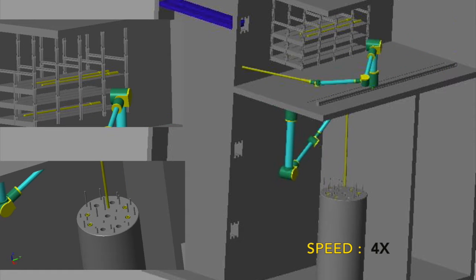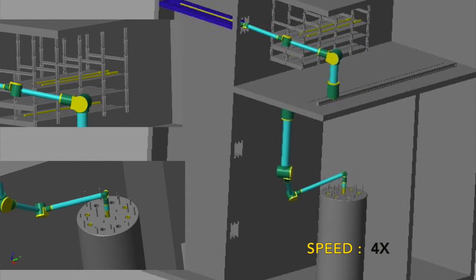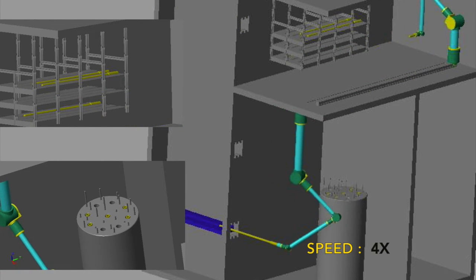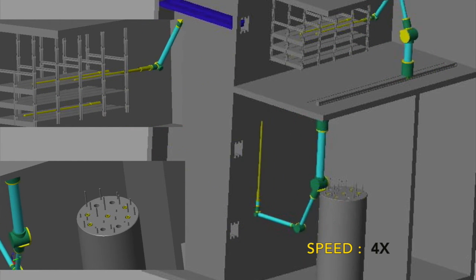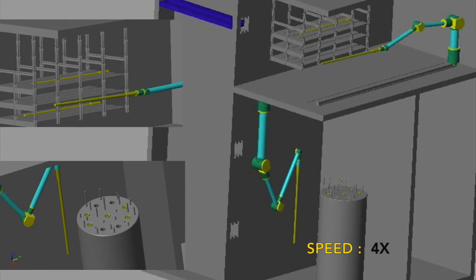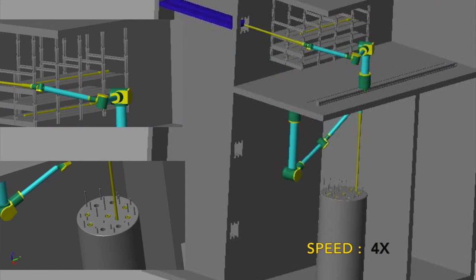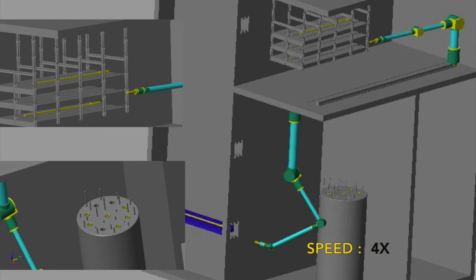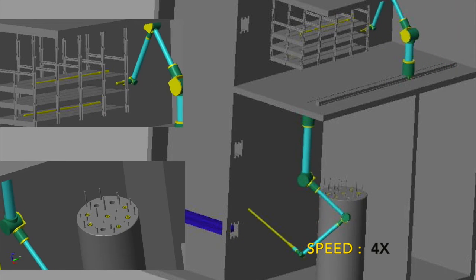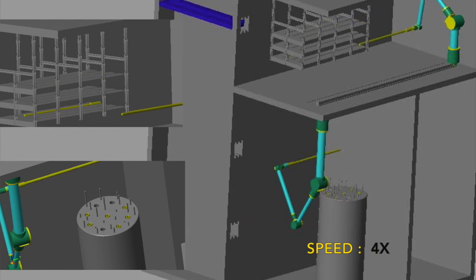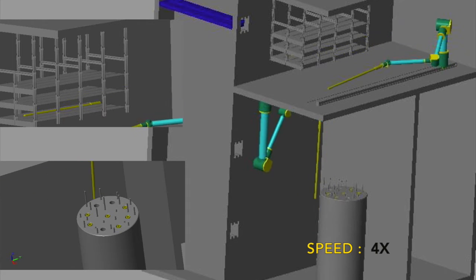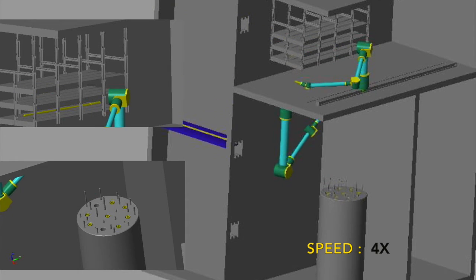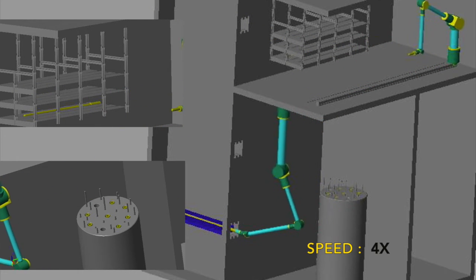The simulation was created in SimMechanics. All the given models for the room and the joints were exported from SolidWorks to SimMechanics in the form of a STEP file. The 2 robot models are built with the desired parameters using SimMechanics transform and joint blocks. A time series data is generated from the MATLAB script, and it is fed into the SimMechanics simulation to drive each of the revolute and prismatic joints.